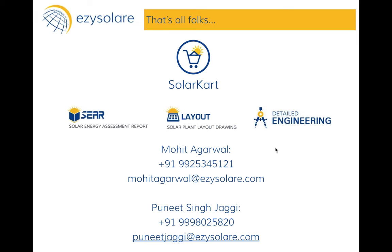To just further elaborate on Shivya's answer, an MPPT is a maximum power point tracking device. It's a device inside an inverter which tries to extract the maximum possible power out of every string. But in case there are multiple strings attached to the same MPPT, then the power output that it is able to extract becomes slightly limited on account of the lowest string which is connected to it. Whereas the more the number of MPPTs, the better it is. I think we have covered most of it already in the discussion.